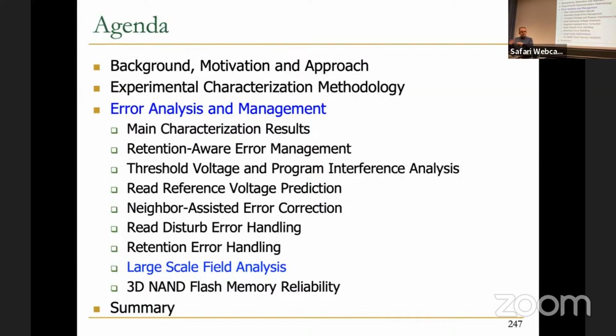But once you know that, okay, position 5 in that bit vector is a leaky cell, for example, probably that bit should be 1, not 0, right? So you just flip that bit and then apply ECC. And hopefully ECC can fix the thing. That's the idea, essentially.